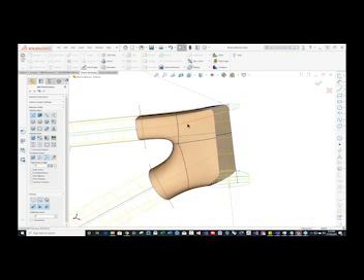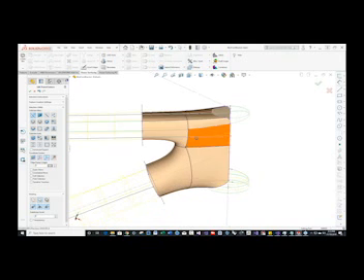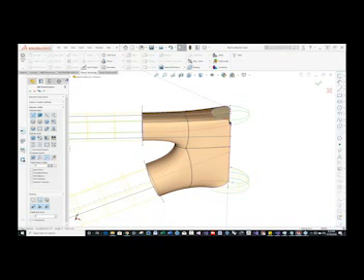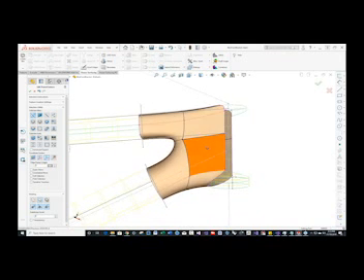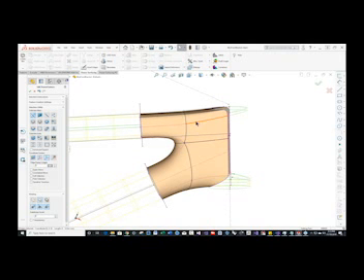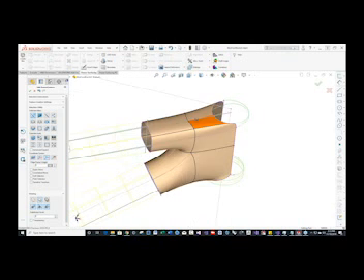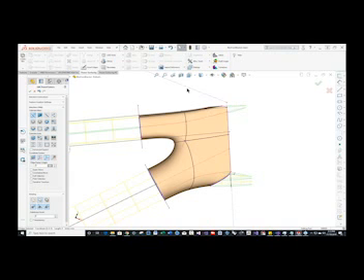But with SubD, it probably took me 10 or 15 minutes to put this whole thing together. And so that's really the strength of SubD, being able to say, okay, I got this surface, I want to make these tangent here, and you notice they're not tangent on the top, but they are tangent on the sides, and so on. And so it was a fairly easy construction. I basically created a box, split it, and extruded a couple things and modified it and inserted a loop here along here, and then that was it. And I think it's mirrored as well. You can see the top edge is probably mirrored.